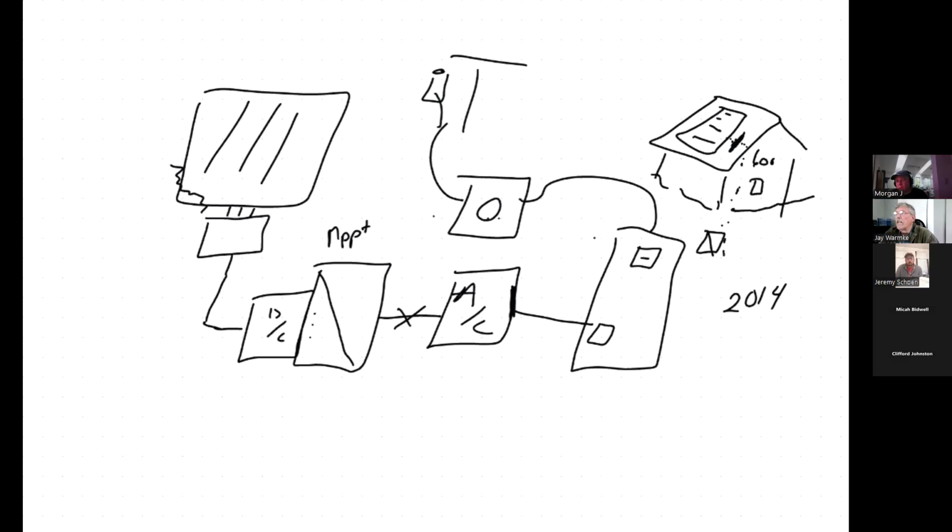So let's just stick the inverter right up there next to the array, and that's fine if you're doing this on top of a Walmart or something like that, where you've got a big flat roof and you can just set that thing right there next to the array. Now it's all pretty apparent. But if it's a regular old shingled residential home, you don't want to put an 80-pound piece of equipment up there on the shingles. It's going to look weird. It's going to not do well.